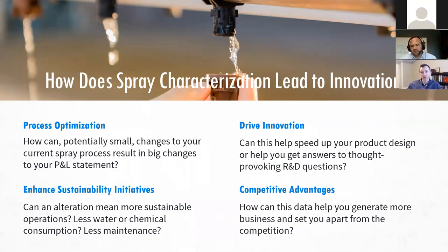Electrostatic charging of droplets certainly helps with that. You can think of paint sprays, where they charge the droplets and everything goes onto the surface of the car, right? But besides that, you're typically going to lose at least some, even a low percentage of the droplets, and potentially a high percentage depending on how things are set up, right? Those fine droplets tend to get swept away, whereas larger droplets will go where you intend. But the larger droplets won't necessarily coat as uniformly, right? So there's typically a balance there that we have to try to achieve.